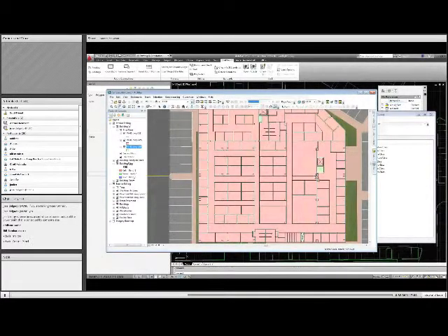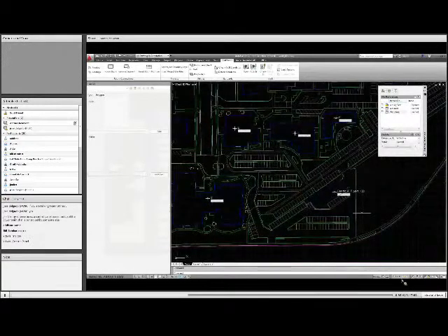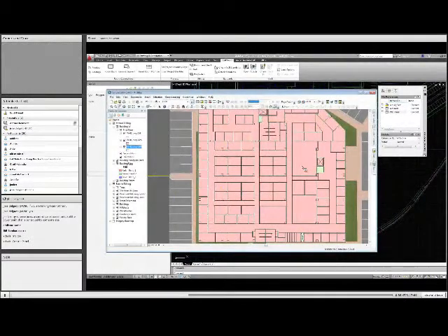So with the data-driven page control, I can actually page through each floor of a building, or each floor of each building if I want. And everything's in the right order, everything's consistent. Because it's the same point, it'll recenter on that point, and every floor is spatially in the same spot on the page, which is really nice. If you want to print out a sort of map book of a building, it's nice to have that consistency, that all the floor plans are in the same location on the map itself. There's even dynamic text for the building name and the floor name, that as the data-driven page index is changed, will update the text accordingly.